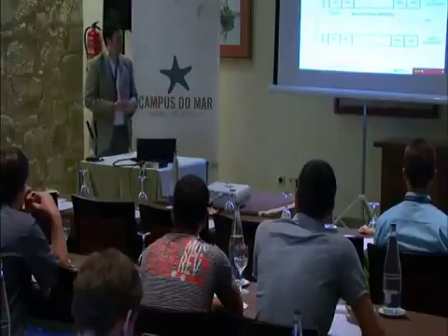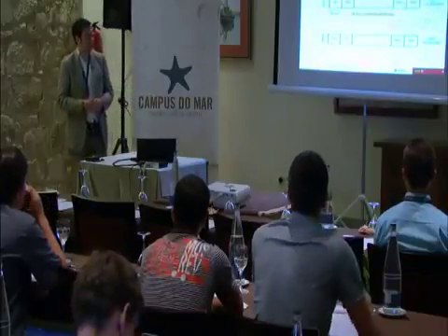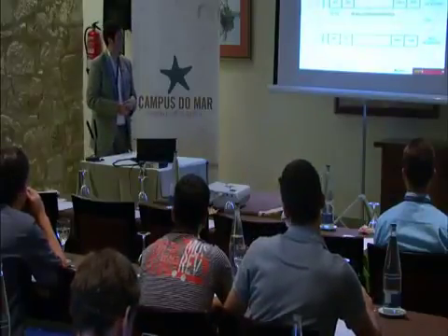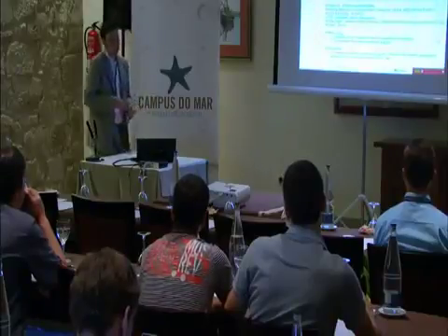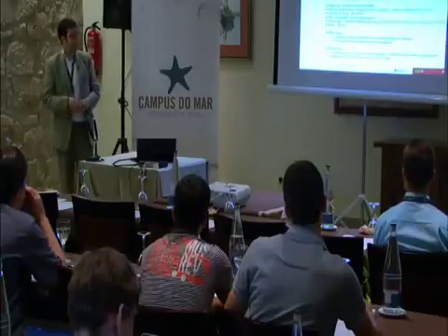And we have two frequency channels, AIS1 at 161.975 MHz and AIS2 at 162.25 MHz. Each channel has a bandwidth of 25 kHz. The data transfer is based on HDLC protocol.